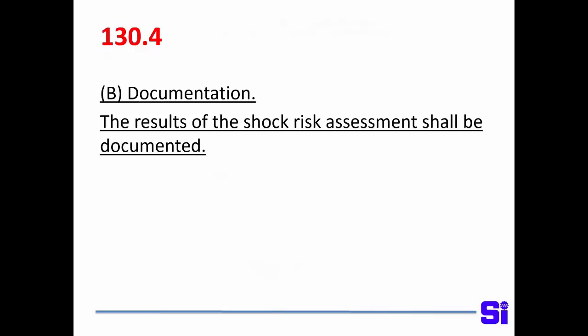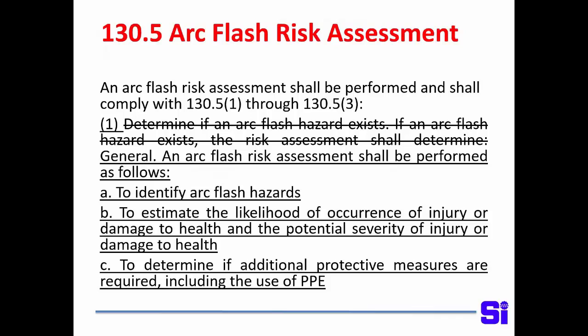Something we didn't have before, but was implied and not stated, is that the shock risk assessment shall be documented. I mean, if you look at the Energized Electrical Work Permit, that is a shock risk assessment that has to be documented. But we just didn't say it. So now we are saying it.